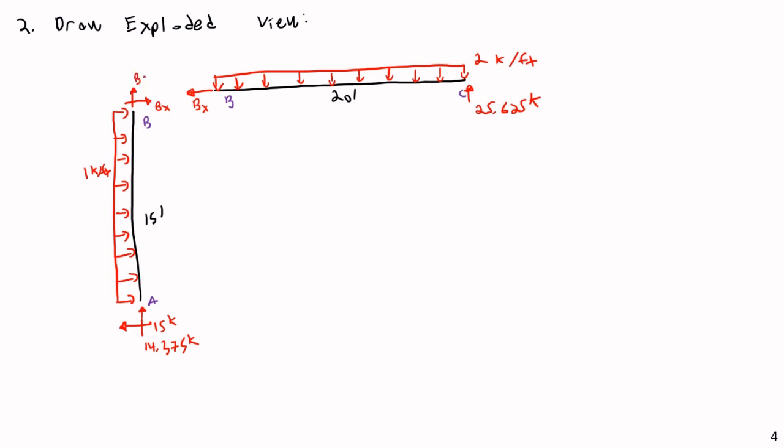So I'd have a By there, and an opposite By here. Then maybe a counterclockwise positive moment here. I would call that MB, and MB here. So I have a horizontal force, a vertical force, and a moment transferring through the beam.